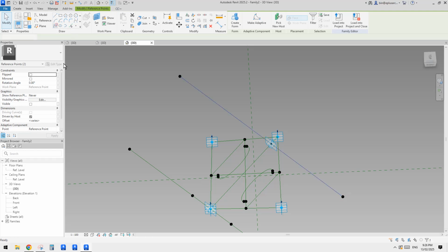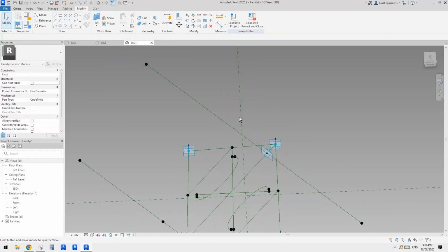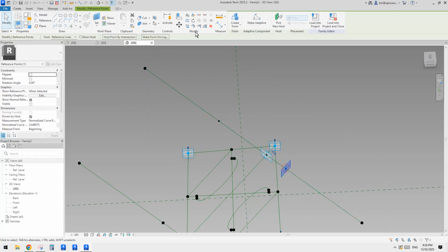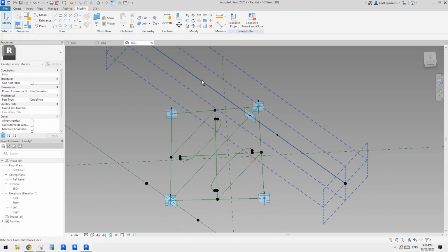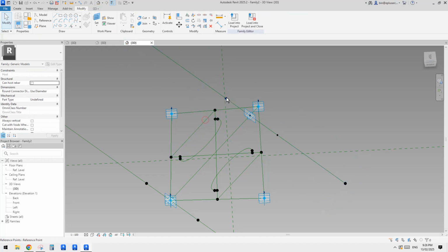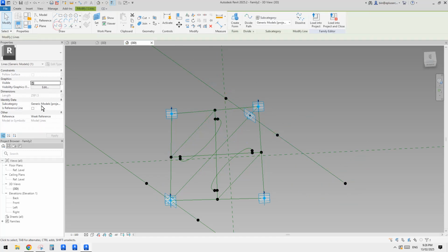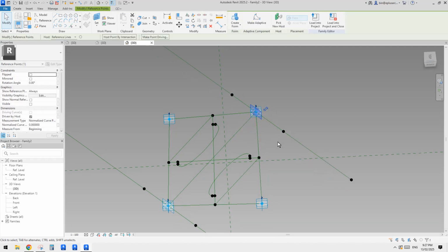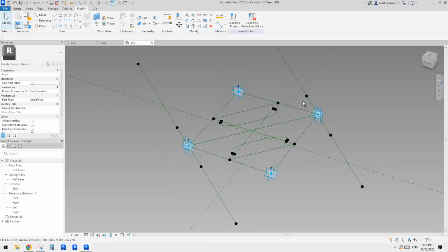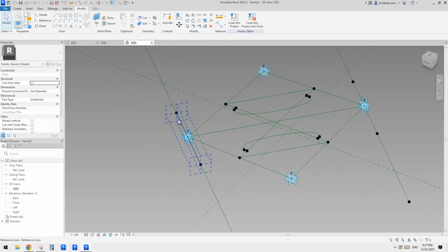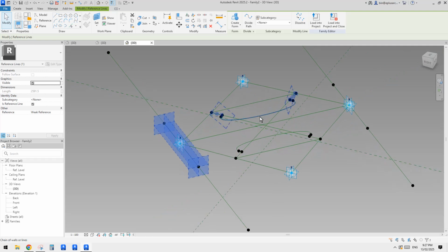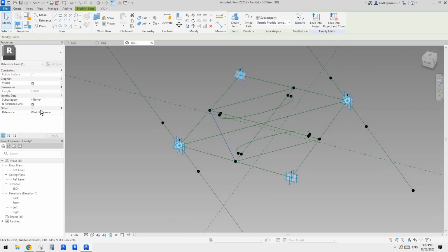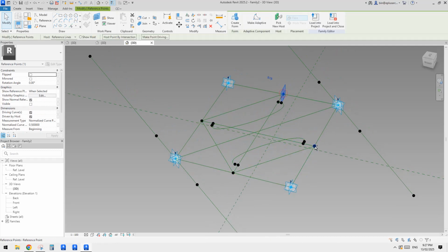Select these 2 points, splice through point, make a reference line, place another point, draw on face, 1, 2, select this point, host bar intersection, another one, host bar intersection. Select this point, create a splice through point, make it a reference line, and then eventually we just drag this to overlap with the point 1. So now we have another profile. And then we might just use these 2 points to create another profile.